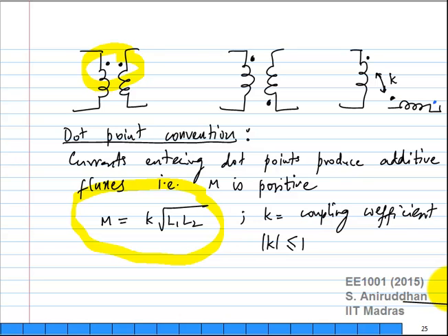Absolutely. That's right. With two linked coils, this mutual effect happens because the flux from one coil, due to the current in that coil, cuts the other coil. The best case is when all the flux from one coil cuts the other, and vice versa, which happens when K equals 1.